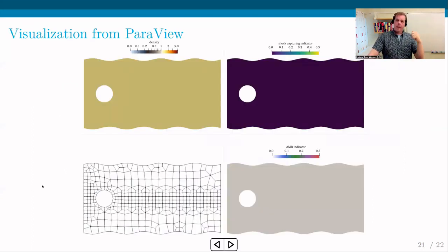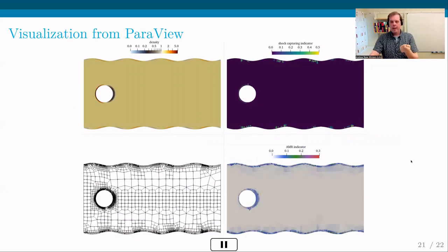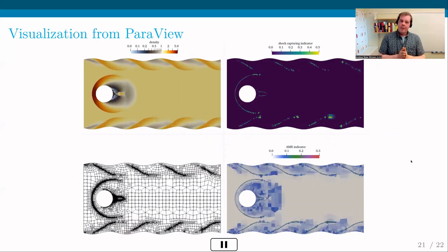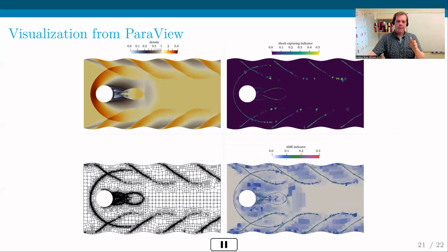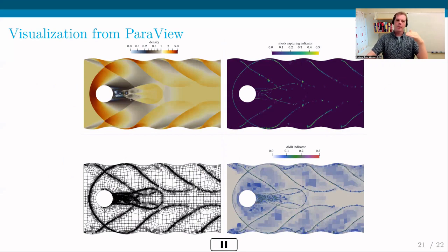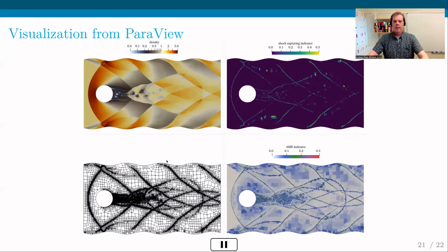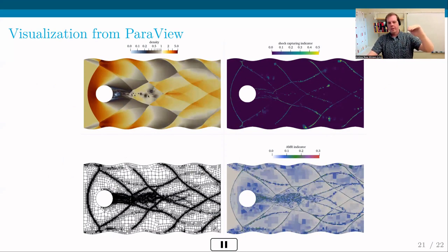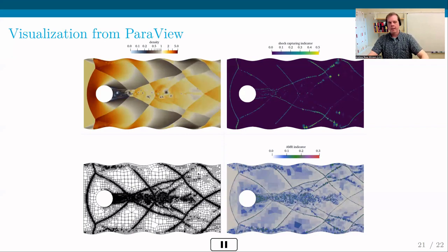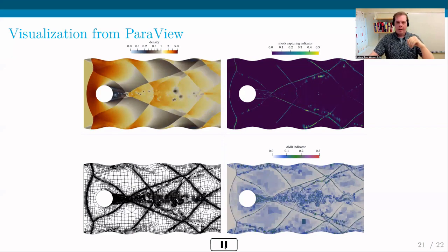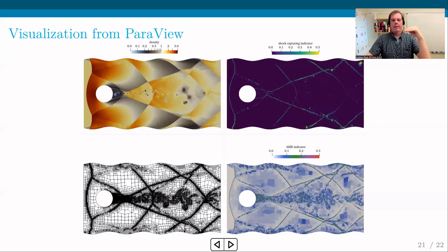So when I do that, I load it into ParaView. I've now run to the final time, which was 2.25, and I can watch how this evolves. And we see that the shocks develop and they start interacting. There's these vortical structures forming behind the cylinder. And here I can pause for a second, that we have these vortices. These are smooth vortices being shed from the cylinder.